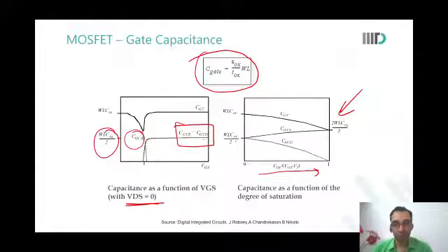Because charges now start to come from the source and drain region, therefore the gate capacitance comes up. So when you're talking about the bulk, you're talking about the substrate only, not between the inversion layer and gate. No. Okay.